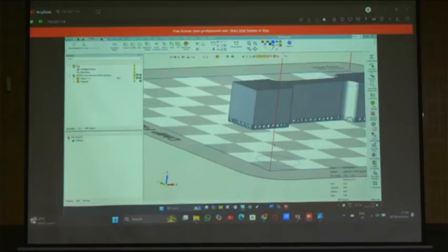Tensile sample is there. Some 30 mm cube I want to print as a lattice. I will add 1 mm thickness of extra base so that I can separate the body. During that time my design space is the 30 mm, and that 1 mm space is the non-design space. I will apply the 30 mm lattice here, combine the non-design space, and print it. So the 31 mm will come. In that, I can cut the 1 mm. Right?